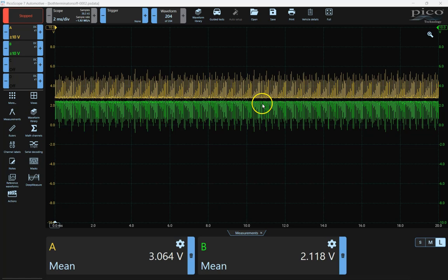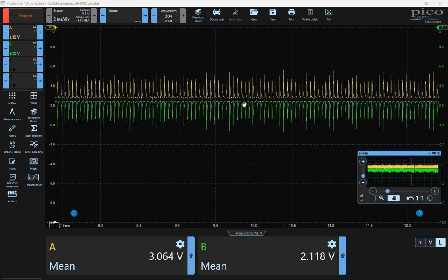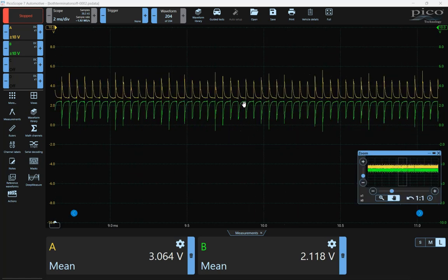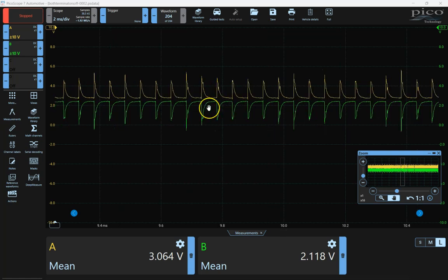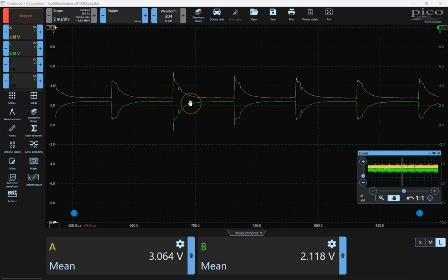Okay, so same machine, and this time I removed both terminators. So I do not have the active terminator nor the so-called passive terminator connected to the harness. We can see that this looks very much identical to what we see on my bench network, where I didn't have the 120 ohm terminators in place. We can see the capacitance of